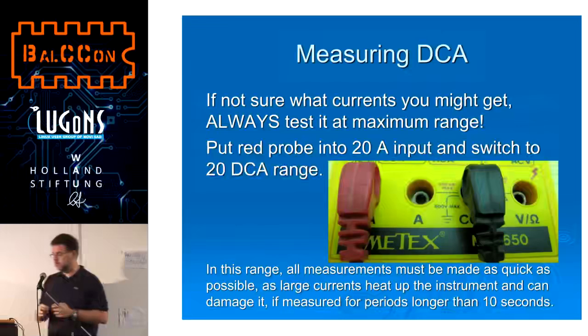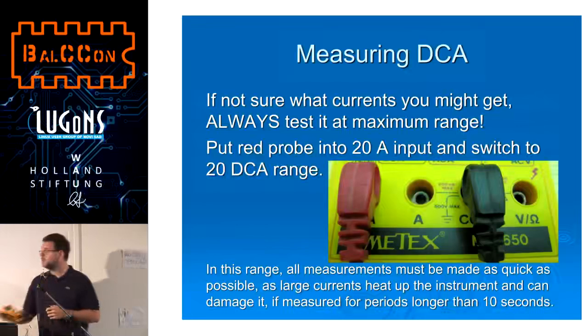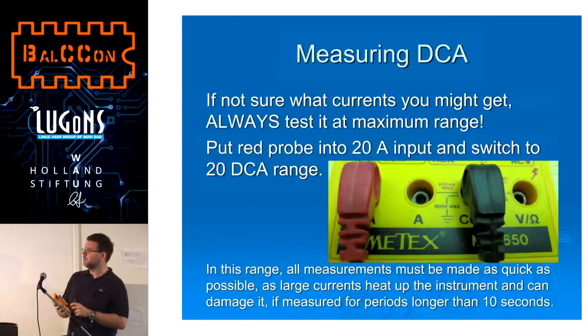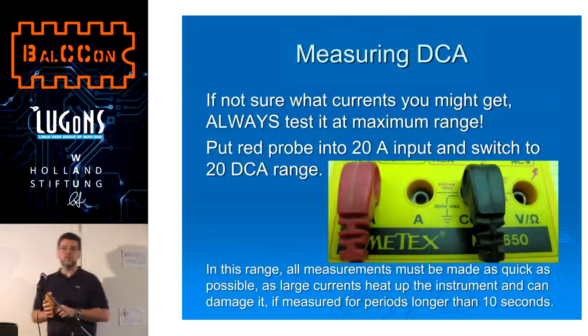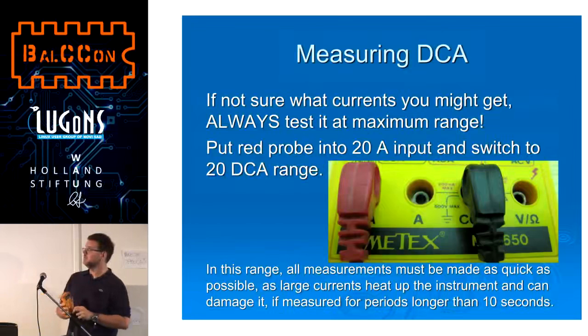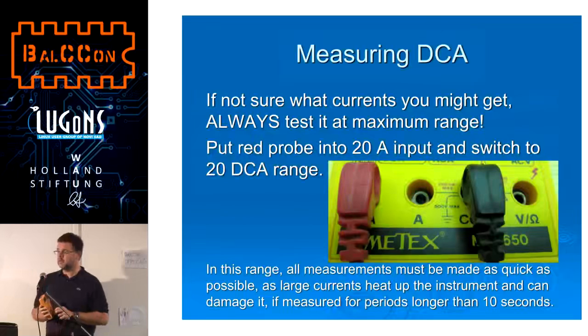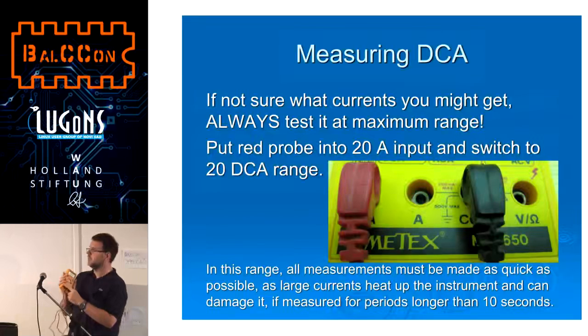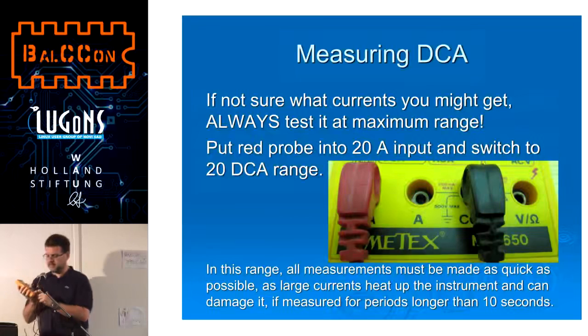It's important to know how to start measuring amps or current. If you don't know the magnitude of the current you're going to measure, always start from the largest, and that's 20 amps.